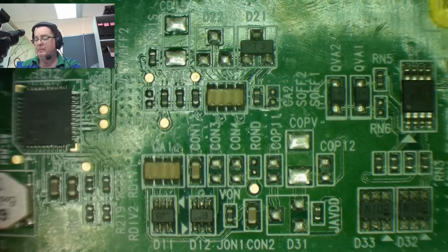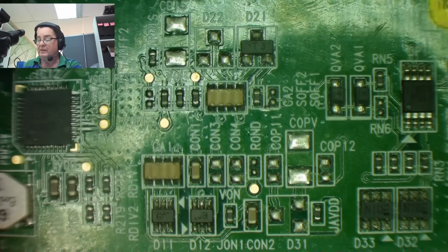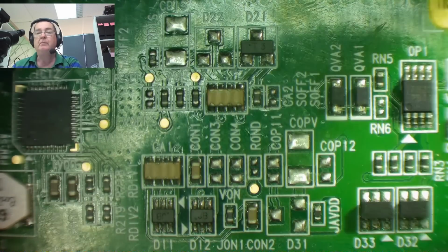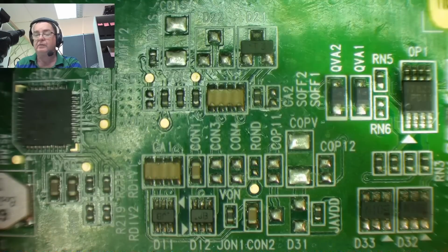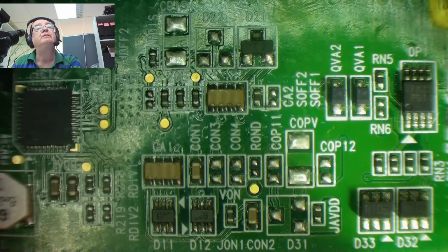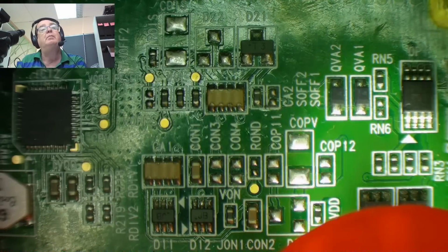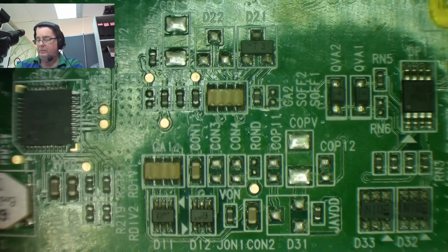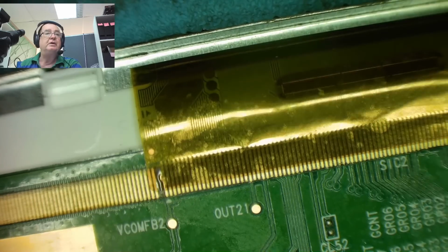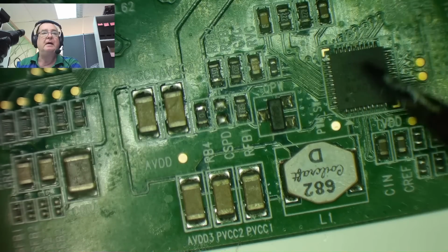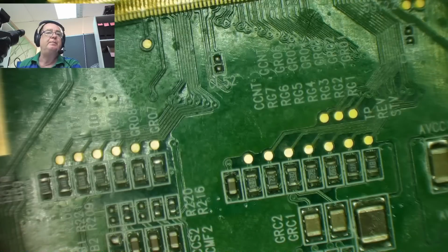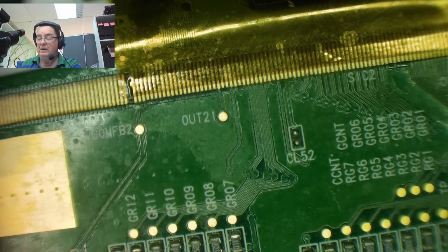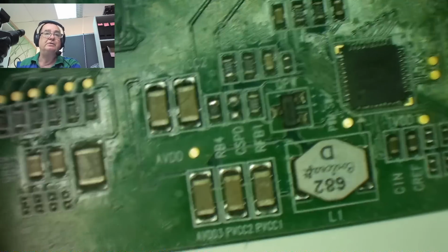This chip here is another one I can't find a datasheet for. It has I7822 as a part number, but having a look on the internet, I can't find a datasheet for this device, unfortunately. So that's not going to help us either. You can see the number though, I7822. But we know that this chip is to do with the gamma voltage, and we've compared the gamma voltages on both boards with these test points and these test points, and we get a nice ascending ladder of voltages.